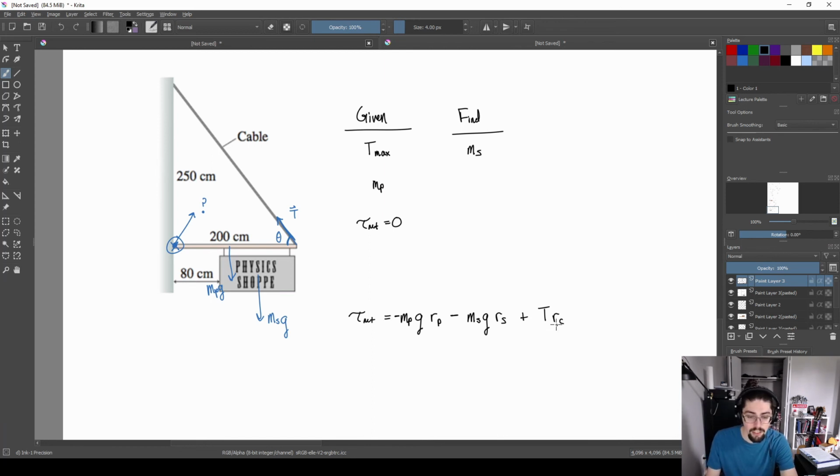What's the last thing that I actually need here? What am I missing? Sine of theta. I am taking the approach where I'm not dealing with the full XYZ determinant matrix, that kind of nonsense. I'm taking the easier way, assuming that I know the magnitude, the radius, and the angle between the two. And then I look at this and I say, hey, this wants to spin me counterclockwise, right? I don't even need the right-hand rule for this one. I can see from the picture, it wants to go counterclockwise. So I know it's going to be positive. All of this equal to 0.